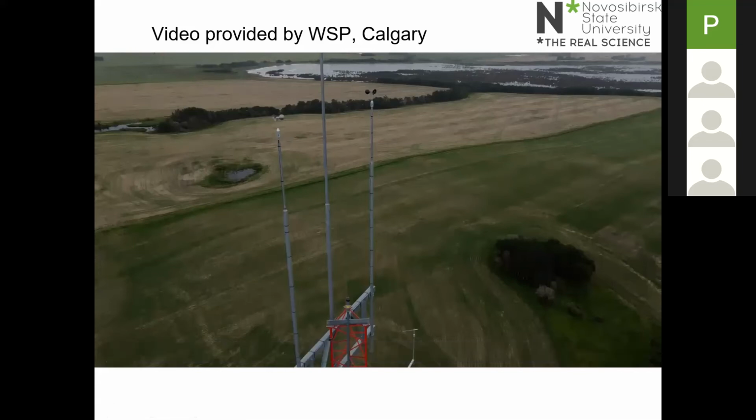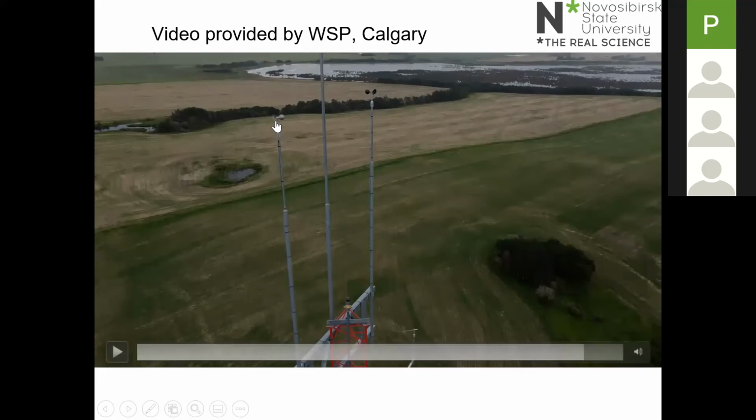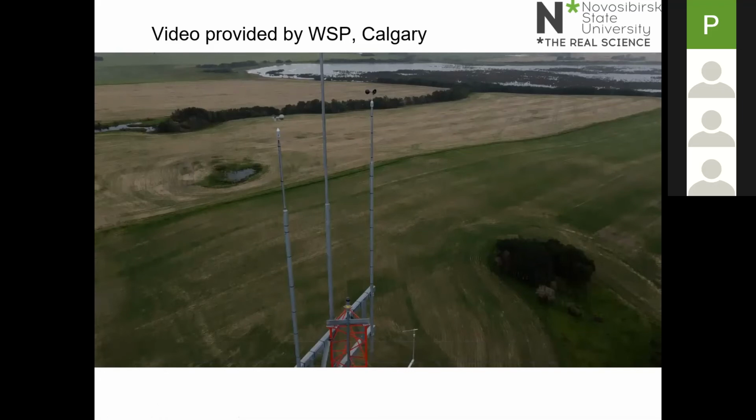And so if you have two anemometers, then what they look at when they're processing the data is any situation where there's a significant difference between the wind speeds indicated by the two anemometers. And if there is, that's possibly an indication that one of them is affected by icing.